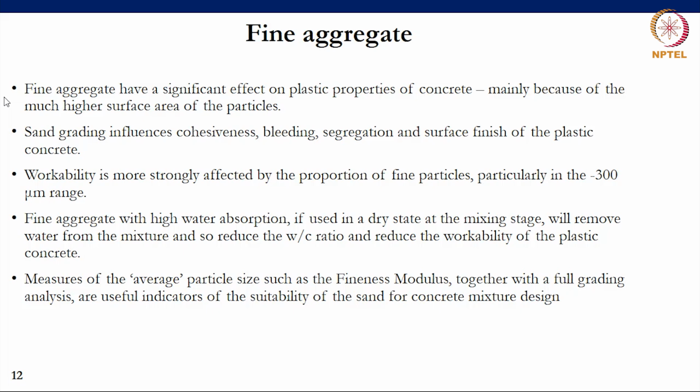Bleeding is a phenomenon where the lightest component of concrete, which of course is the water, rises to the surface because the heavier cement and aggregate particles are settling. This causes water to rise to the surface. And if the bleeding is excessive, you will actually see pools of water forming on the surface of the concrete that has been freshly cast, compacted, and surface treated.